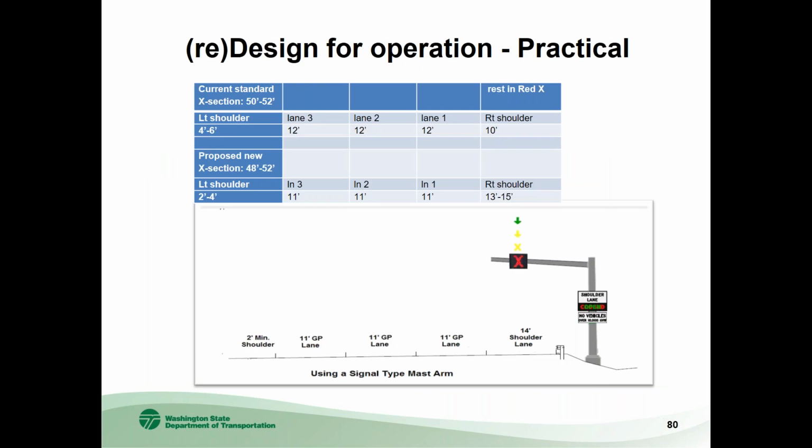So in the future, we will probably look more into this kind of ATM Lite. We probably will not be deploying a lot of full gantries across the roadway, only because the cost to maintain traffic signs over live traffic is so expensive. We might have a few gantries in the existing corridor where we extend the corridor a little bit, but otherwise we'll try to go with ATM Lite, which means using the dynamic shoulder more.